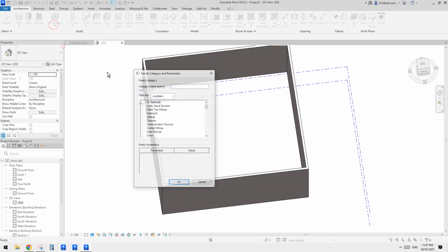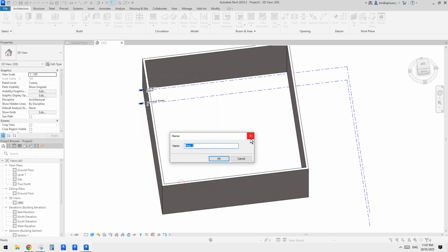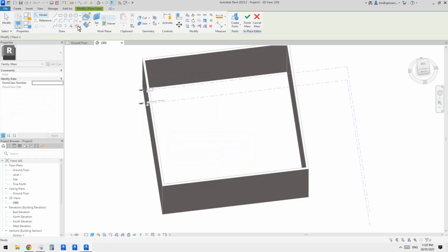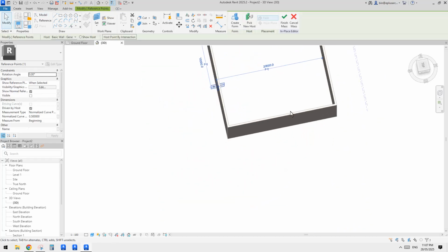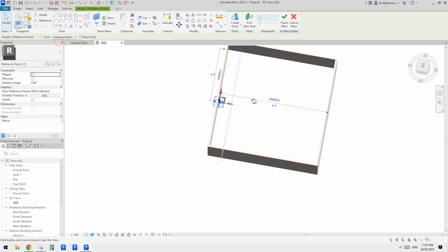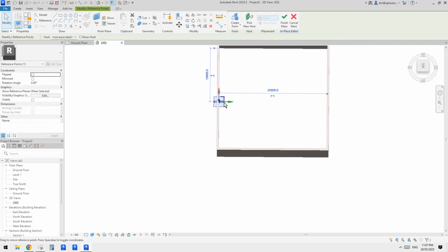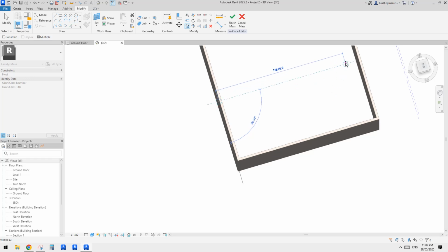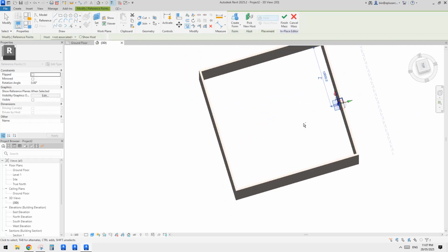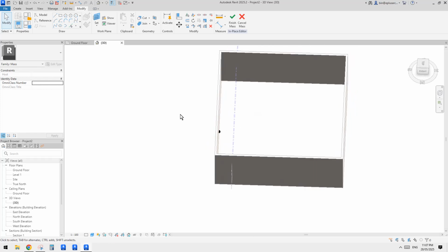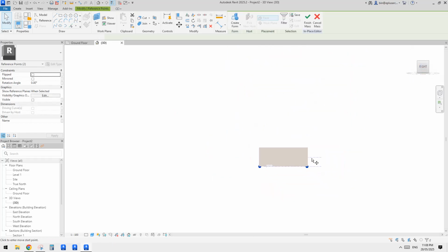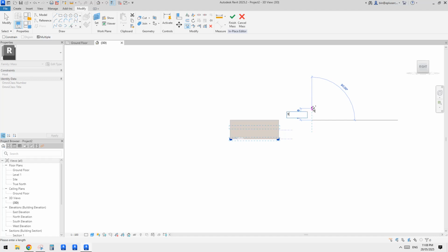So modeling place mass. First I'm going to place a point, draw on face, and I can snap onto the midpoint on this wall, and then I'm going to change this one to not associated. So now we can copy this one to the other side. Okay, and then I'm going to copy them up by a very small number, for example 10 or even like 100.